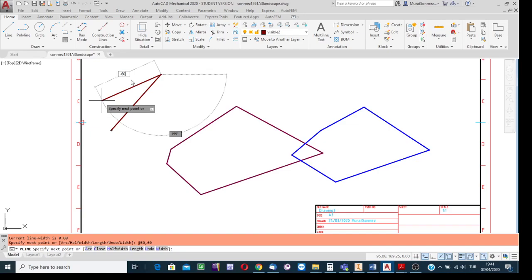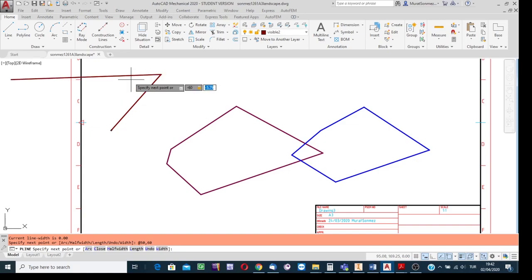It is to teach the software that the written number is not length. Obviously length cannot be negative, but it is delta x. Click not the tab key but the comma key of the keyboard. Okay, and then AutoCAD understood and took the arc simulation away from the screen, and is waiting for my typing.